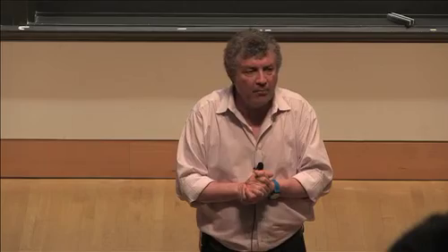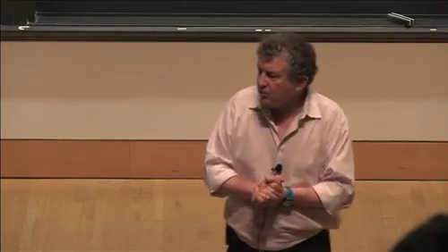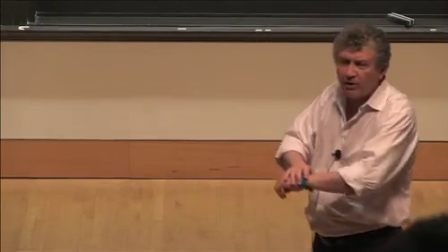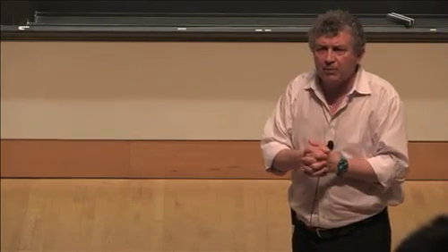The problem is that it's only good when the Lewis numbers are unity. Otherwise, the definition of Z is not totally consistent, since you have to allow for variable diffusivity. So Lewis number not 1. There is some use to that mixture fraction, and a lot of people like it because, of course, it simplifies the problem greatly. With that, I will stop here, and after the break, we're going to move on to droplet combustion and spray.